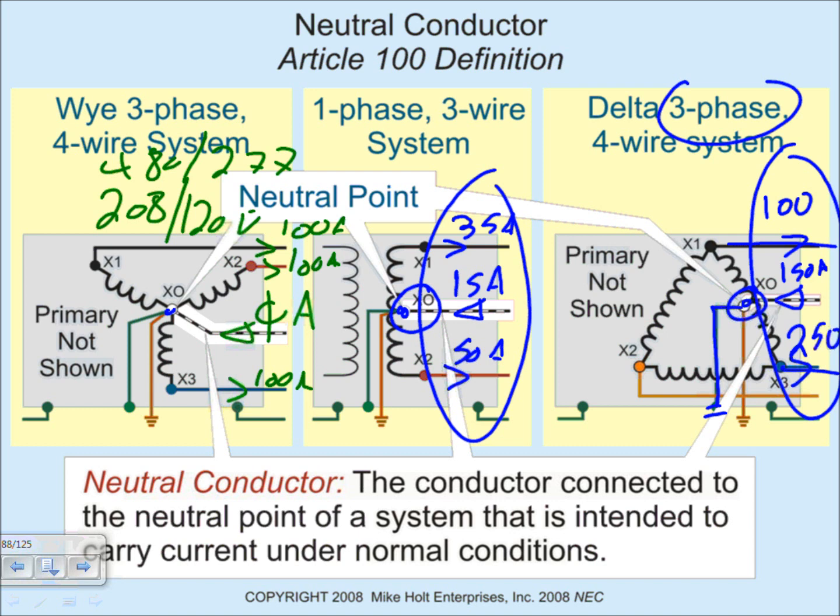Any question, guys, about the neutral point or the grounded conductor? Why do we care about the grounded conductor? Two levels of voltages. It's the most important thing. One level safer, lower voltage. One level higher, phase to phase. You can burn equipment at a higher voltage, which is less safe but more efficient. The higher the voltage, the more efficient the system is, but the more dangerous. So I can't put 480 here and allow my kid to plug into an outlet at 480. Any mistake at 480, you're dead, versus any mistake at 120, you have a chance to survive.